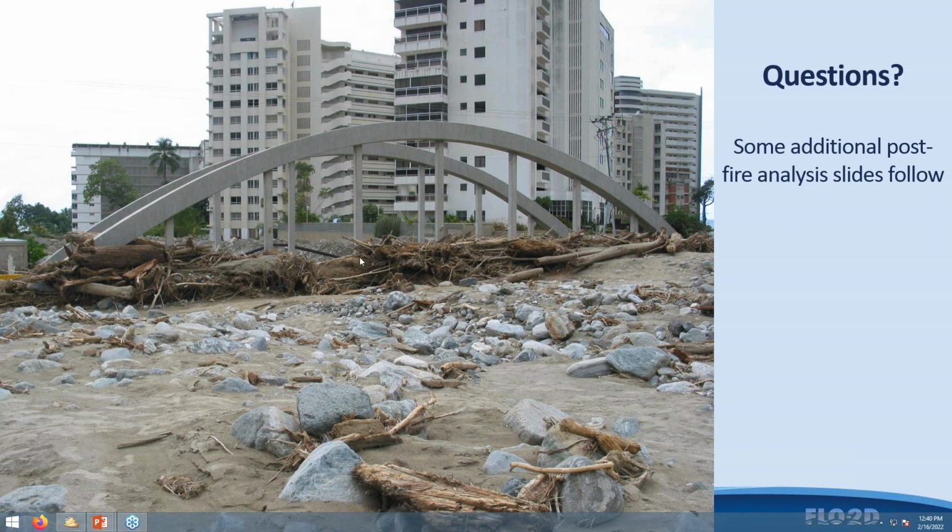Are there additional considerations to use with modeling lahars, which are volcanic type of mudflows? The answer to that is, I would say, see if you can do some laboratory analysis to get the viscosity and yield stress. Now, that's a little complicated, but the viscometers that are available will allow you to do an analysis like on asphalt.